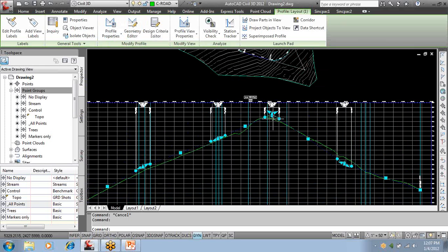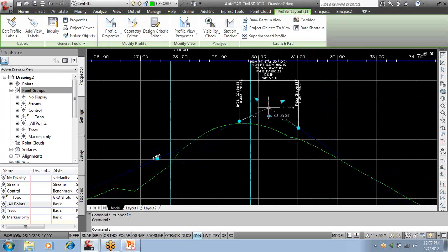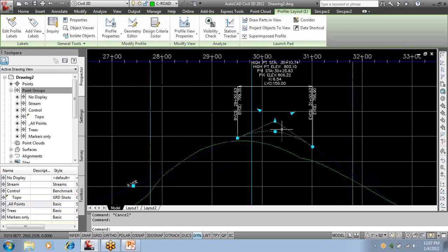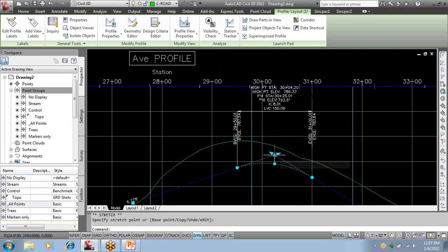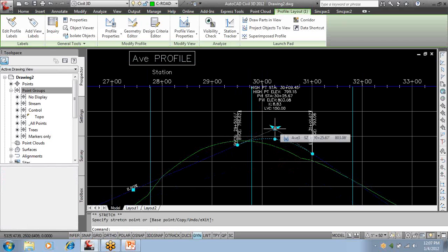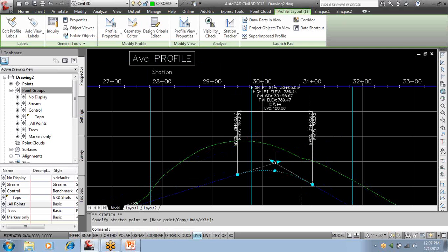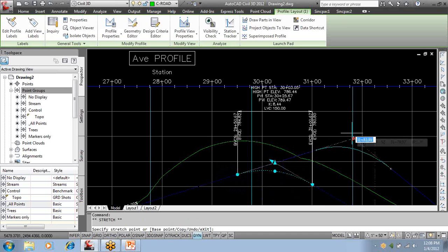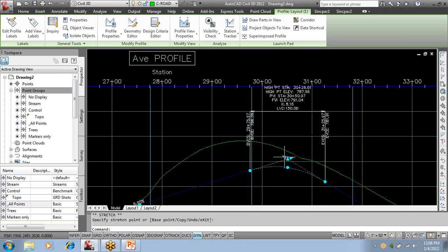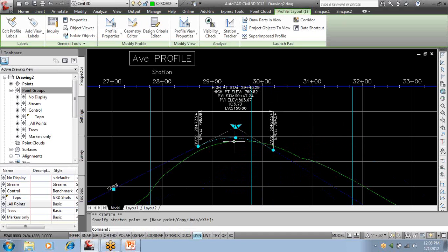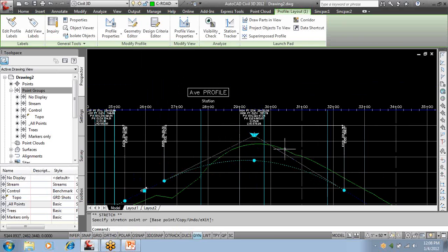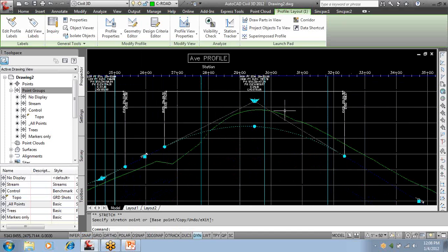We can tie it into exact curve elevations. We can simply watch the radius, 150. I can go in here and move this up and down. You'll see that didn't change. All I did was change the elevation, right? Okay. The other ones, maybe I just want to hold this grade, but we want to change it. Notice it's going to lock that on there as well. So you can simply drag this around, hold minimum and maximum grade, and this goes in as well. If I want to change the radius, I simply select this one. It changes the radius. I go back in the editor, I put in the exact one, or I set it to only go to 5-foot increments.